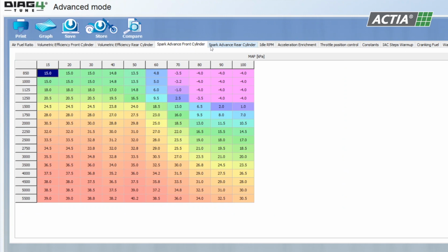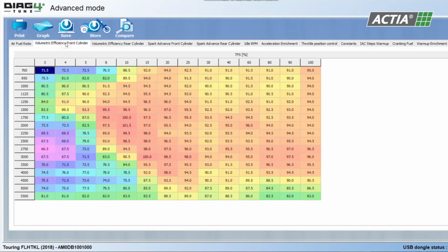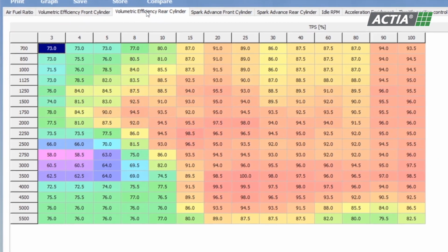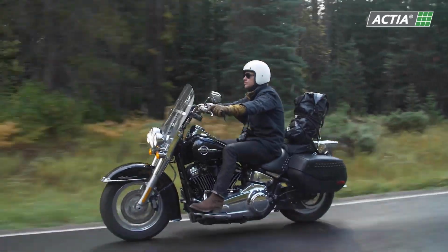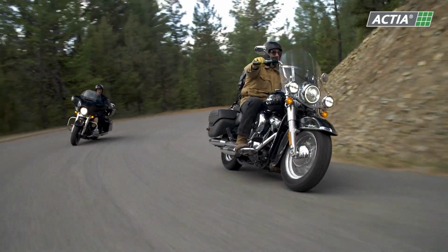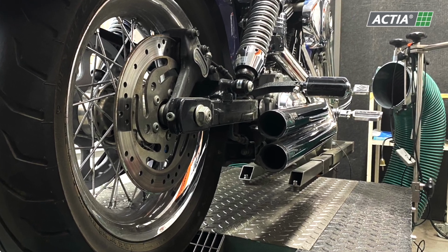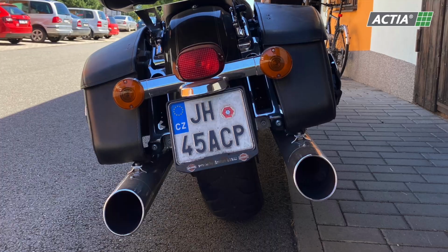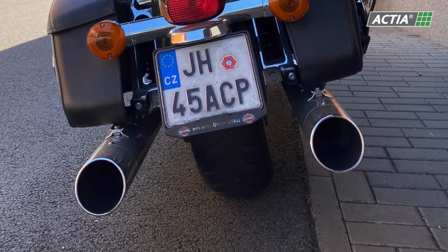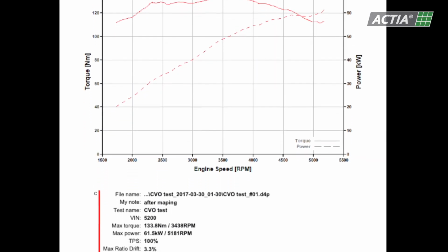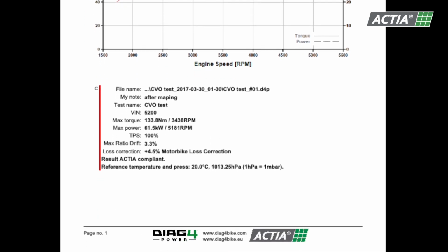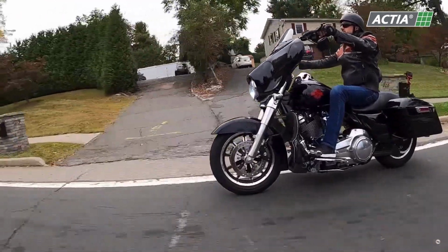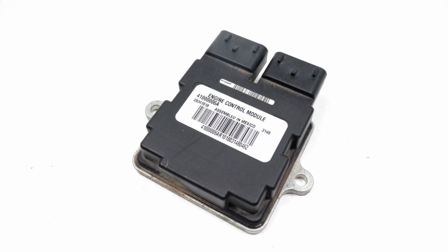The capability of individual engine cylinders to take in air is described by VE maps. VE means volumetric efficiency. These maps will be described in more detail later. What's important for now is that these are tailored to the factory configuration of the engine. Modifications to the exhaust and intake have major influence on the engine's ability to take in air for combustion. In many cases, these modifications even help improve the actual VE maps of the engine cylinders. This creates the right conditions for increasing performance parameters as well. The problem is the EFI control unit does not know that.